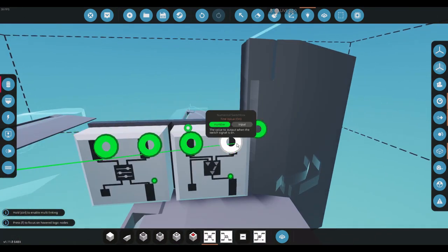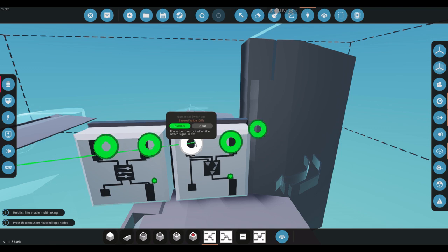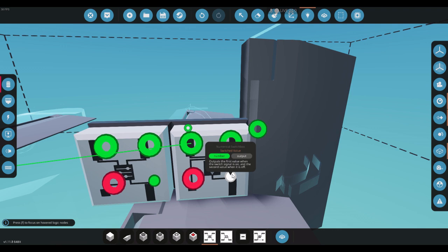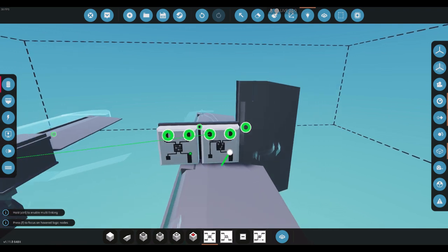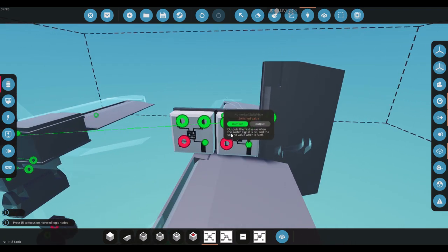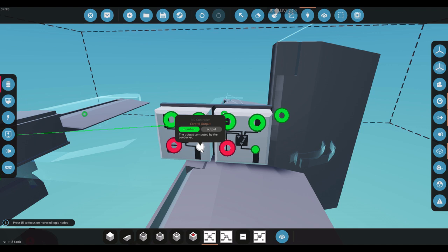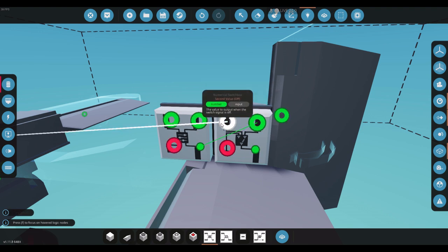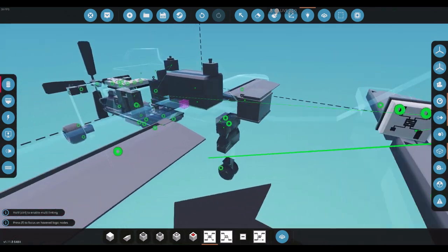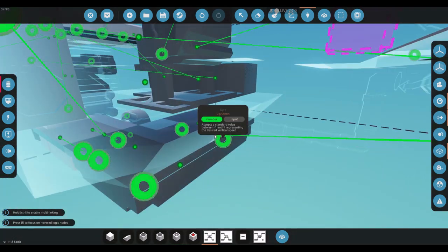You're going to come to the numerical switch box and go into the off value. By default, we will be using the pilot W and S controls to control our pitch. When we turn on our system, it's going to be controlled by the PID, and that'll be controlling the pitch of the plane to get our desired altitude. So you can take PID output, control output, and that's going to go to the on value.